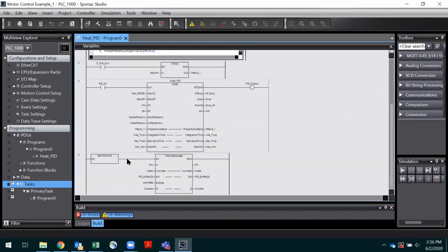So I assume anytime that you turn off the start AT and then turn it back on, it reruns the auto tune for a new set of parameters. Correct. Yeah, it'll reattempt the auto tune. So every time you cycle power on the PLC, will you need to auto tune, or can you make those variables retained? No, it'll retain them. Do you have to do anything for it to retain, or is it automatic? I don't believe on the PID block you do. There are things like the PID block and the retentive timer block that will be retained for you. Okay.